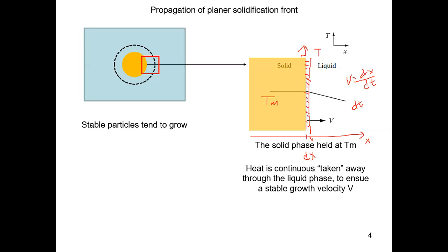That makes sense, because if you look at water, it has a disordered microstructure, right? What is heat? Heat is the difference of the enthalpy. So if this is the enthalpy of the liquid and this is the enthalpy of the solid, at the melting temperature, which one is going to have a higher enthalpy, the liquid or the solid?